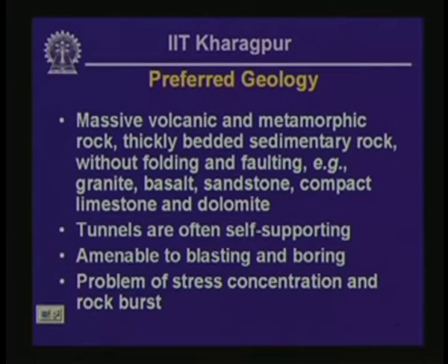Now, if you construct a tunnel in that kind of geological setting, then such tunnels are going to be often self-supporting. The tunnel can be constructed by either blasting or boring, but here you have to account for a certain type of problem associated, and that is associated with stress concentration, because in this case the rock mass is relatively strong.